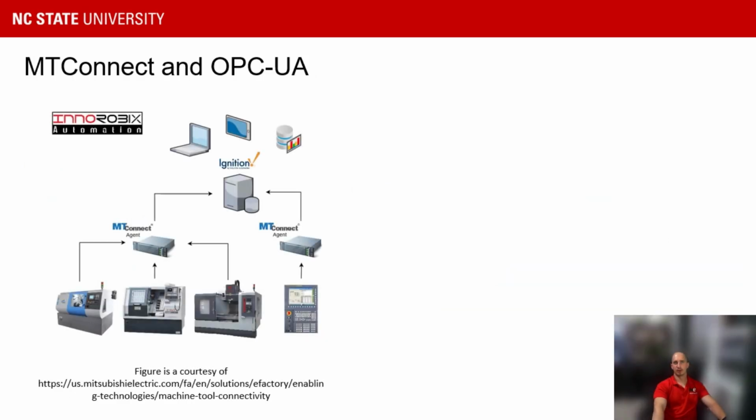One well-known way of accessing the data of metal cutting machine tools is via MTConnect. It is a read-only, royalty-free communication protocol that uses XML and HTTP to request and deliver data from MTConnect-enabled devices. The benefit of this protocol is that it does not require any proprietary software or deep knowledge to access the information from the equipment.